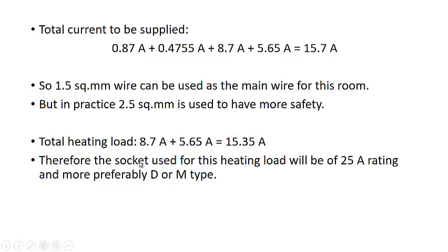That means the socket that is to be used for this heating load should be of this rating, and more preferably a 3-pin socket or 3-pin plug type. So in this case, it will be quite safe to use a socket of rating 25 ampere. But you might have seen that in our homes we usually use only a 15 ampere rating socket. We rarely use this 25 ampere rating of the socket.